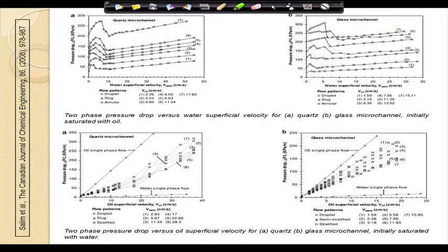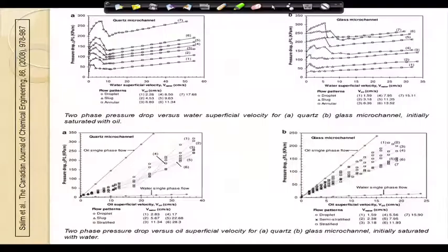So, all these factors combined, maybe the reduction in effective viscosity as well as the expansion of the water film, the expansion of the oil film as it flows along the water plugs and then meets the oil plugs below the water plug, possibly this particular reduction occurs.